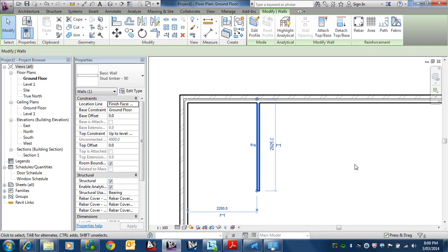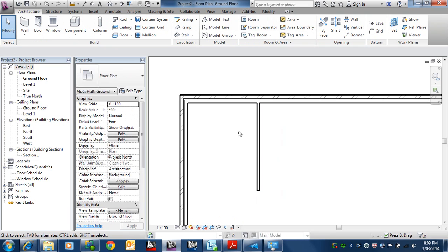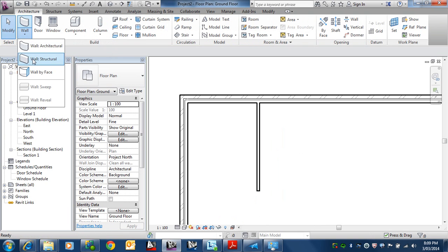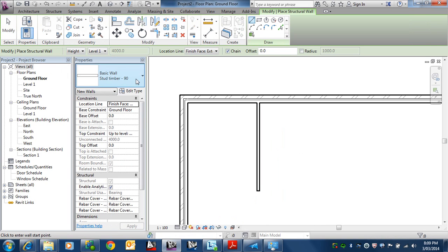Anyhow, maybe I should have, for example, gone like here. What options have we got? Finish. If I went finish face interior, perhaps that would have been okay. But it's not like it really has an interior and exterior. It's just, but he still treats it that way in case you put in that wall as an external wall, but it's an internal wall. Both sides are the interior anyway. All right, so we'll leave that then.